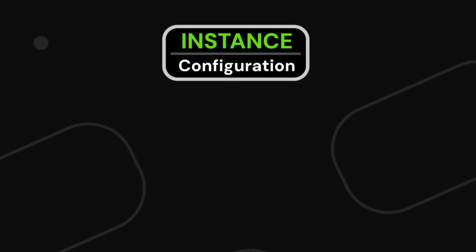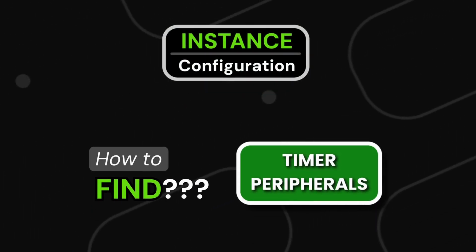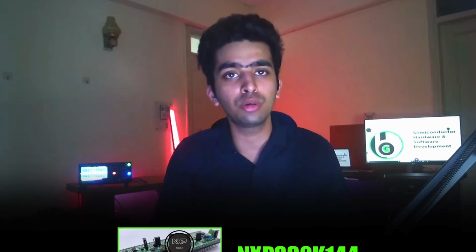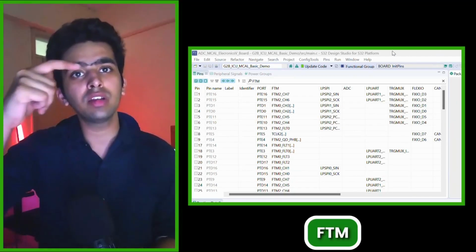Now this is the instance configuration, and how to find the instances in a timer peripheral. Now for the pins, which pins have an FTM or timer peripheral mode: for that, you go to the pinout diagram. Like in the case of the NXP S32K144 microcontroller family, in the Design Studio there is a pins view. In this you will see that there is an FTM.